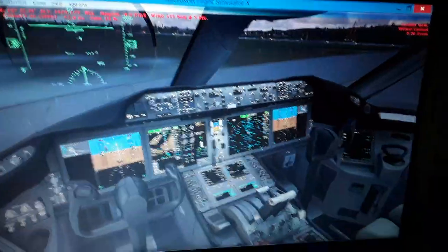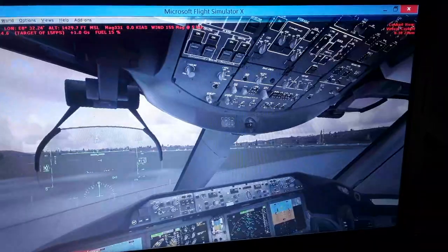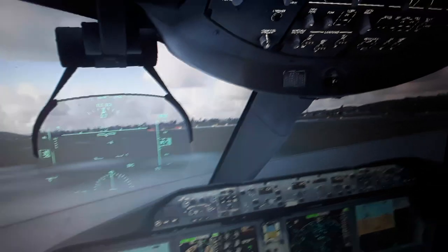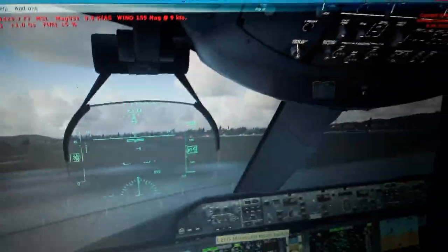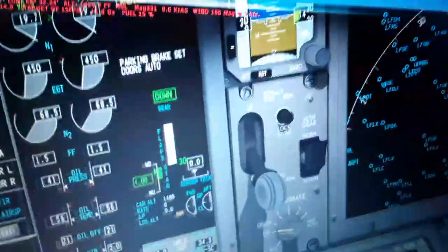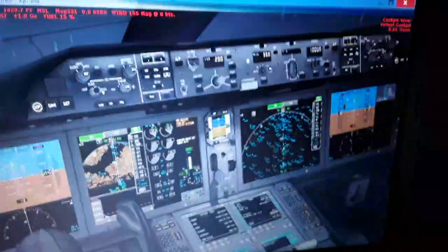So we have a few more things to see. Flight control computers over here, flight management computer, actually the head-up display also, we'll see later in flight. The overhead panel, so it's a few things only left. For us you can see the engines, left versus right engine indications. So we go in the flight management computer now to show you how to create a flight plan, and we input all the data of the aircraft for this flight, and includes the empty weight plus the passenger plus the cargo plus the fuel on board.